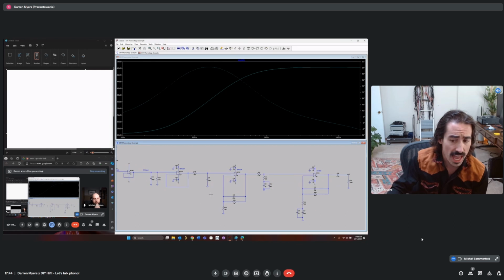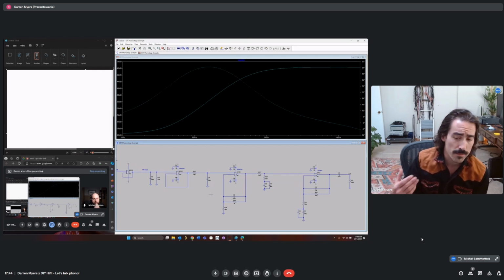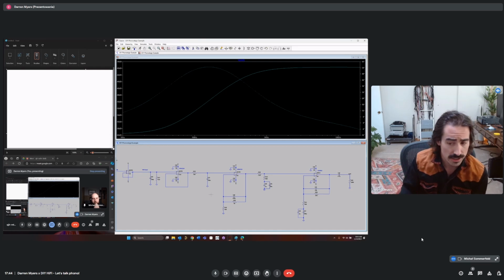So it's another compromise, but some might argue that it's a better compromise than the ones above this, just because you get the advantages of running these amplifiers with a constant correction versus frequency, but at the same time having some of the overload advantages of introducing that 75 microsecond time constant earlier.